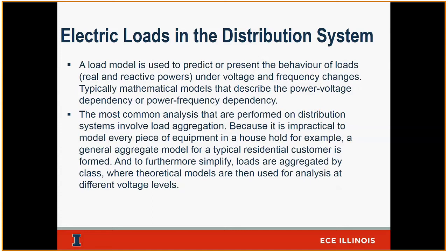It could be pulling a lot more VARs compared to my residential load. It's VAR needy. Also, its characteristics in terms of whether it has a lot of motors and how it reacts to changes and deviations in voltage. That's one of the things we look at closely when looking at the distribution feeder, to better understand what composition of loads I have. That way I have a better understanding of what type of analysis I need to do when studying the circuit.